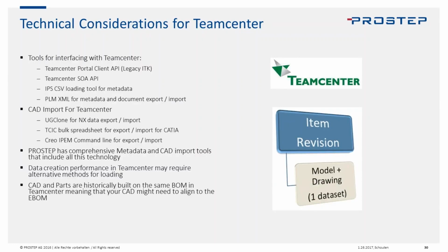These are the standard interfaces for the data that you need in Teamcenter. You need to reuse and respect that interface for a couple different reasons. One is that if you do it through just the back end of the database, it might not be in there correctly, and maybe legally it voids your warranty on the data that you put in there because you didn't put it in through the interface effectively. But this is the best way to get CAD data in, through the native interface